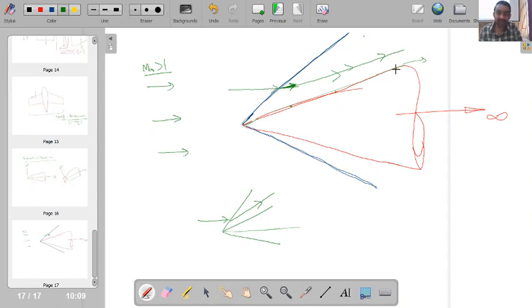this surface can be considered as nothing but, if this is my vertex, say if I put a light source over here, from this light source some ray will go like this along the surface. So that ray I can consider nothing but a constant property line if I assume constant properties on the surface. Similarly, if I put a light source that will be emitting multiple rays, so I can have one more ray over here, something like this, then I can have one more ray over here, something like this.